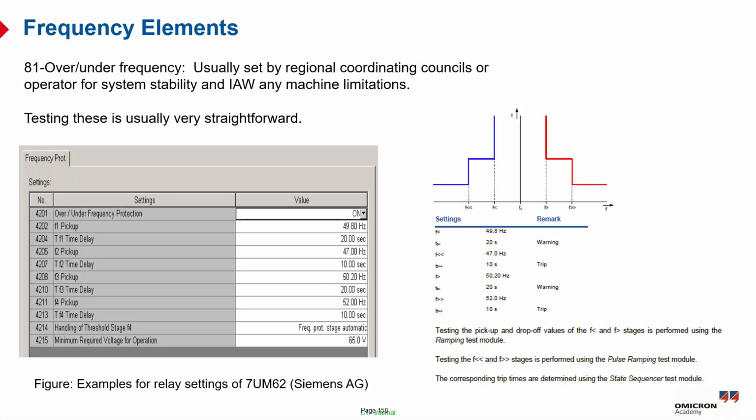So the frequency protection, or the 81 in the ANSI code of protection, protects the generator and turbine from operating beyond their safety frequency limits. Both can only tolerate a limited range of deviation, with low frequency reducing generator output and posing risks of mechanical responses in the turbine blades, especially in the steam and the gas units.